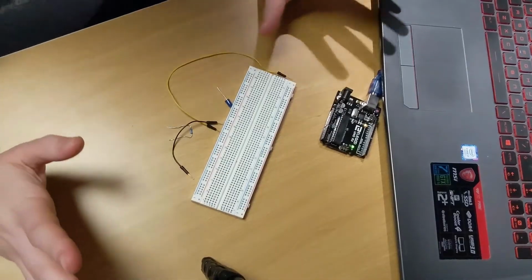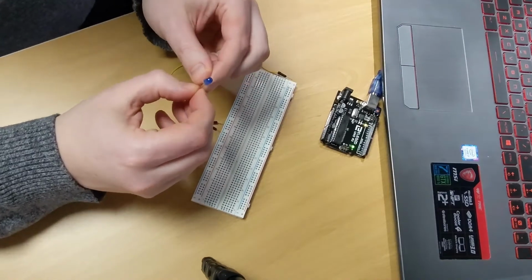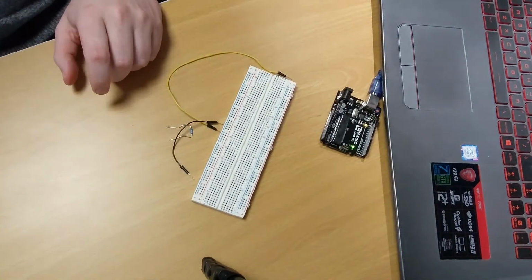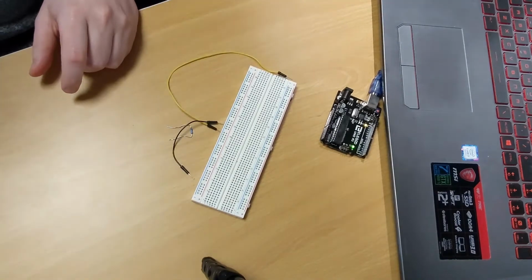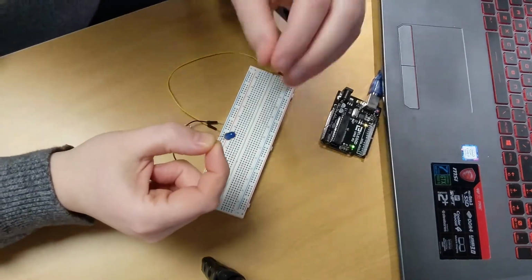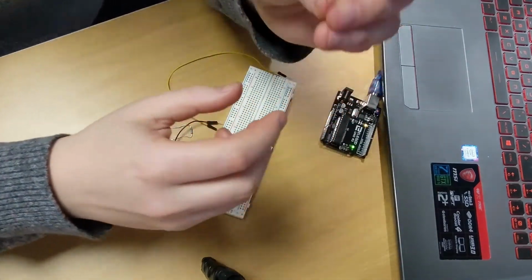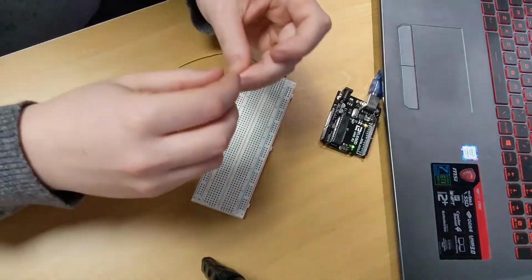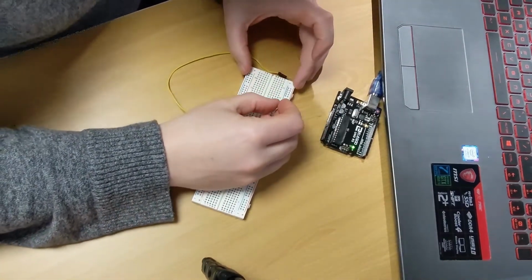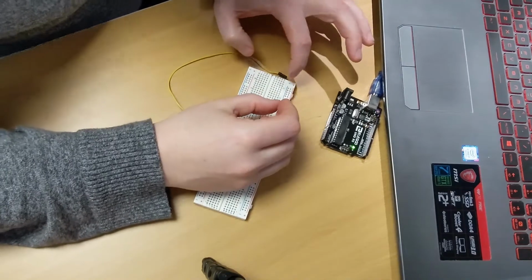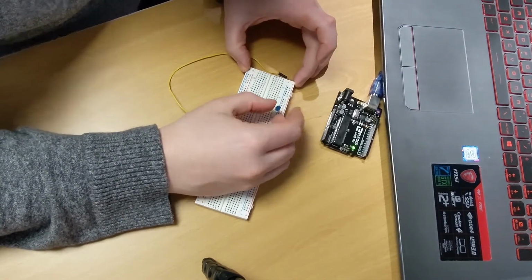Okay, so let's start building. So the first thing I do is get hold of my LED. Now I hold the LED up to the light, and we'll talk about this in a little while. We'll go into a bit more detail on it. But if you hold an LED to the light, you'll see that there's a big flag and a little flag. Now the big flag tells me that that is the negative end. So if I hold mine to the light, I can see that this side of the LED is negative. So I'm going to place that in my breadboard with the negative onto the hole next to this blue line. Okay, so I'm going to push that in there.